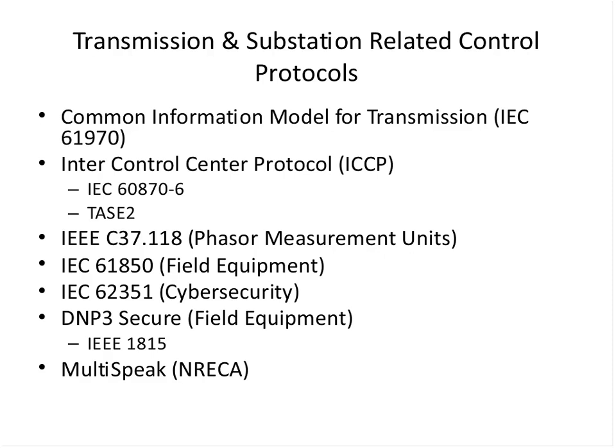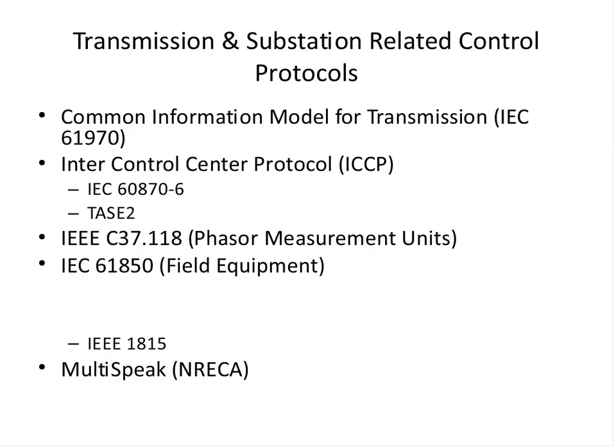Remember, 85% of the infrastructure out there in North America still uses DNP3, still uses serial interfaces to go to most of their remote terminal units and the intelligent electronic devices. So while we're talking smart grid and we want valuation of our companies and all that, and we're excited about it, recognize where the reality is today and be flexible to grow with it. And that's first understanding, identify. Remember how NIST tells you in their cybersecurity framework, first thing you have to do is identify, which means figure out what your ecosystem has. All right, moving right along.